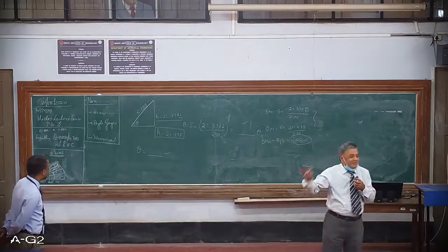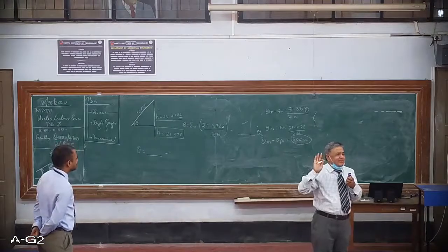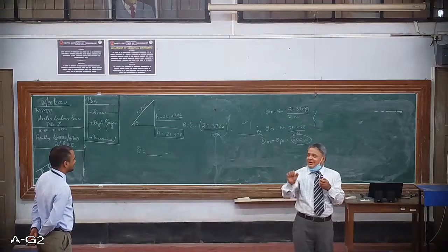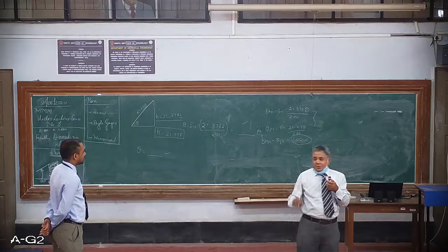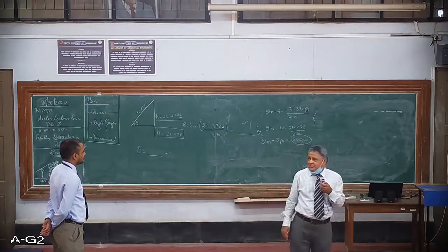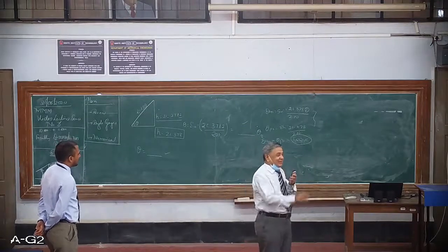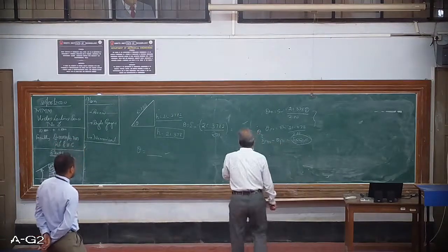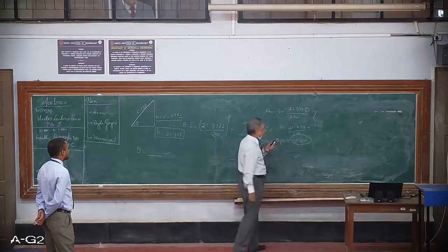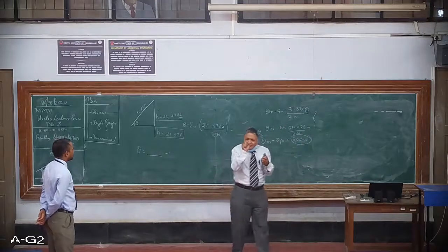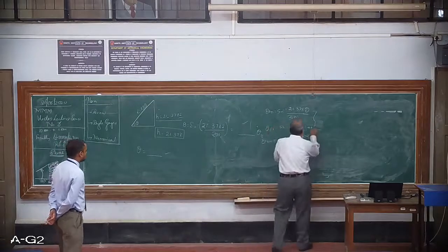Now this error, nobody has contributed to this. The sine bar is perfect, our surface plate is perfect, we have everything in place, but only because of non-availability of the slip gauge, there is an error. Industrially, there are two points. If I can sustain this error, then there is no problem. But if I cannot, then I have to build 27.378 plus.